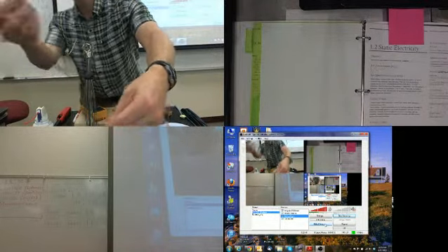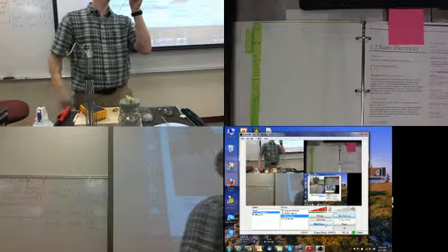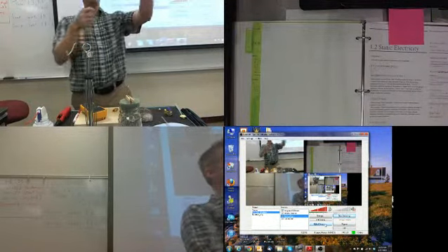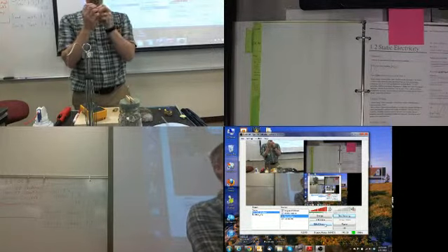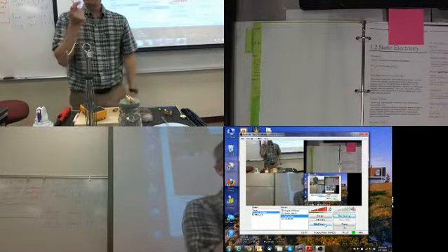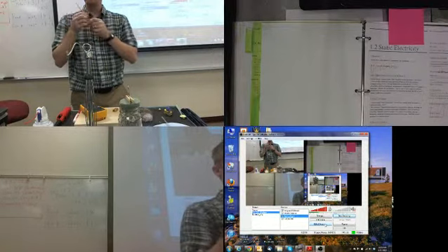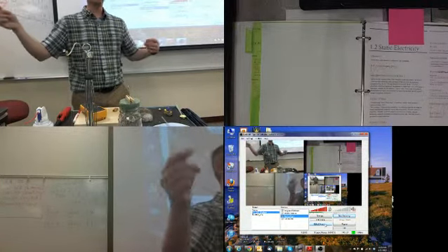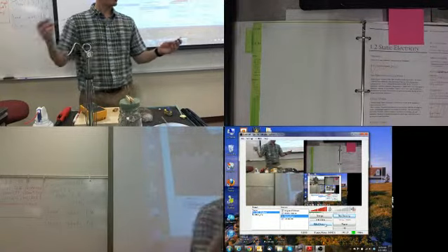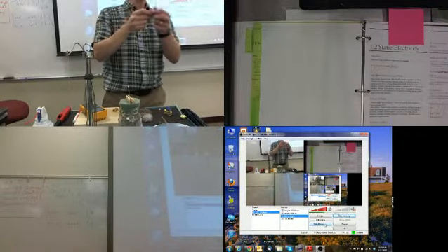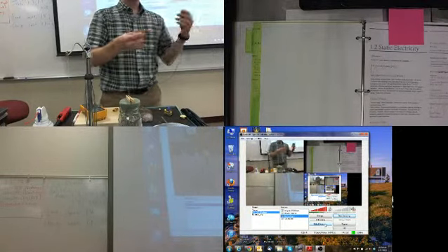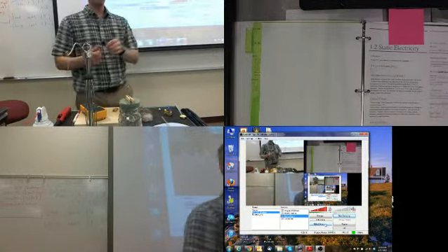What it is, it's just two different types of wire with this little piece of metal. It looks like just a little solder blob right there. It's actually a little weld. Just two wires with a different type of material right there. That's all it is. It actually measures temperature. We use it in electronics to measure temperature. There's one over there on that $2,000 piece of equipment that we have. You would take this and use Kapton tape to tape it to whatever you want to measure the temperature of, and then you would bring it outside into some sort of a voltmeter.